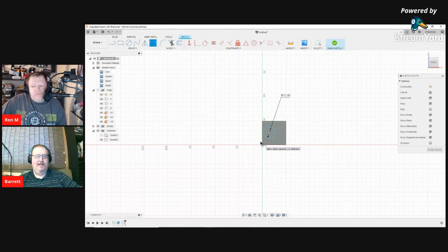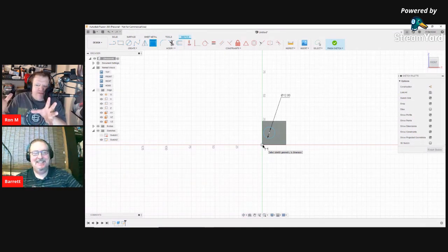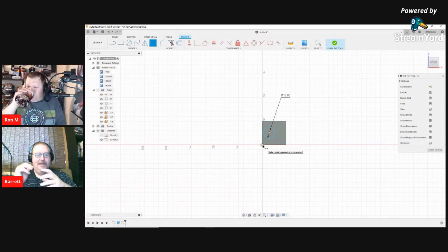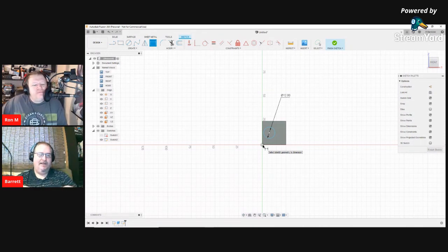Think of it as a base point. It's the reference off of which everything else is referenced. Okay, so it's basically the starting point. It's the starting point. So wherever possible, you need something in your drawing referenced back to the origin. You can then reference all kinds of things off of other parts of your drawing. But in order to get your model fully constrained, you have to have at least some part of your model connected to or on or dimensioned from the origin.